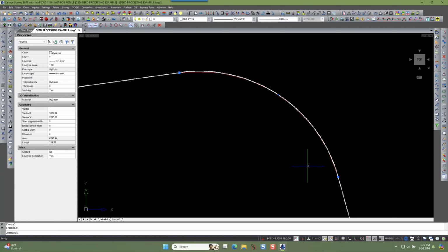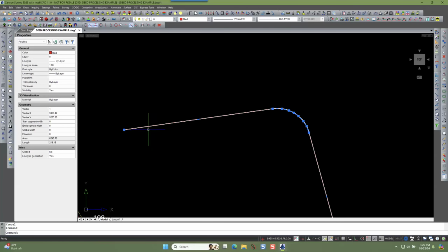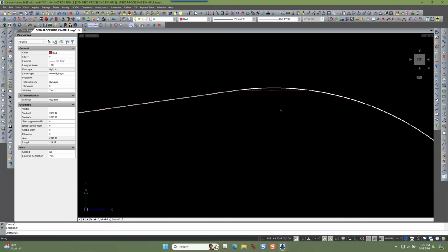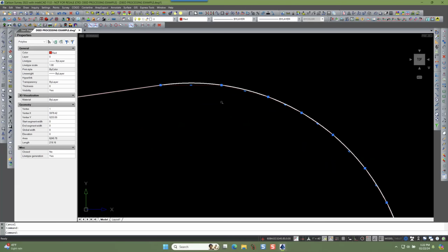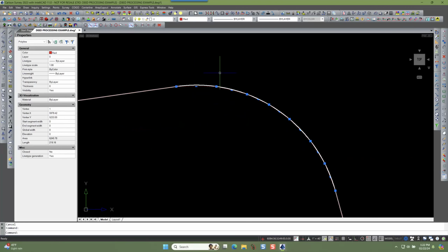And so the only way that the CAD system can represent that is by converting it into something like this, where it goes along the same elevations for the straight parts. It hits the curve and it says, now I need to go from this elevation down to this elevation on the end. And I need to represent that with a series of little chords along that curve. So how do you want me to create this chorded approximation of that arc?